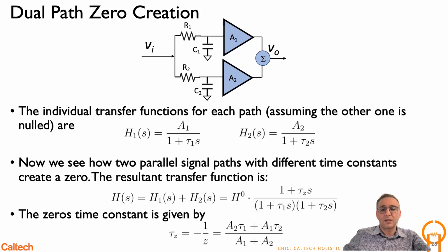And if you write them and form a common denominator, you will see that you form a zero. And this is interesting and obvious because zeros should depend on the choice of the input and output and where the signals are, but the poles shouldn't, because they're natural frequencies of the system. That's why all of the A terms have those H's, the transfer constant, but none of the B terms have those. That's an interesting pointer.